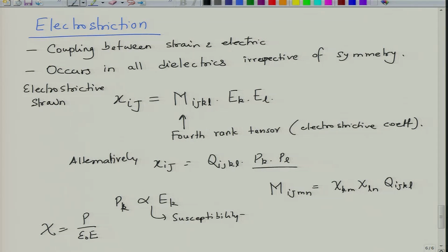So, we are not going to get into details of electrostriction, but basically it is something which is present in all the materials, and it can be present in addition to the piezoelectric effect in the materials. Okay, and sometimes the piezoelectric effect in ferroelectrics may also be explained as a sort of electrostriction based on spontaneous polarization. So, there is a possibility that the polarization present in the material gives rise to electrostriction, which is manifested in the form of the piezoelectric effect.